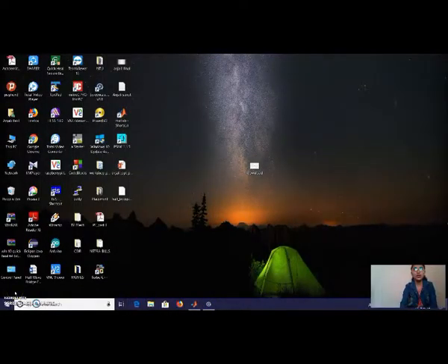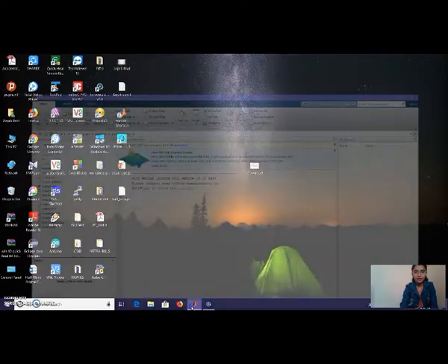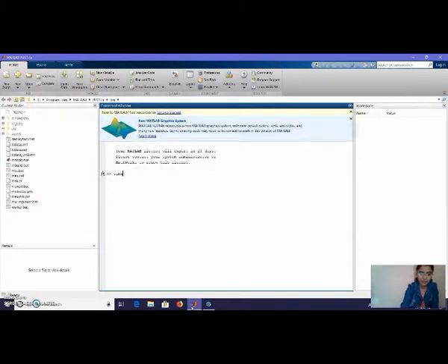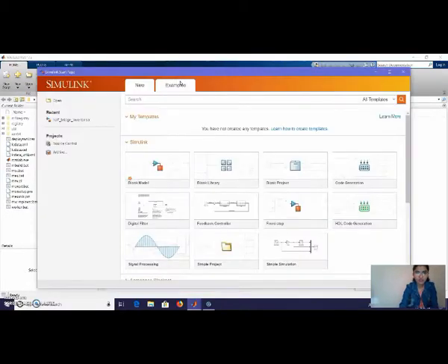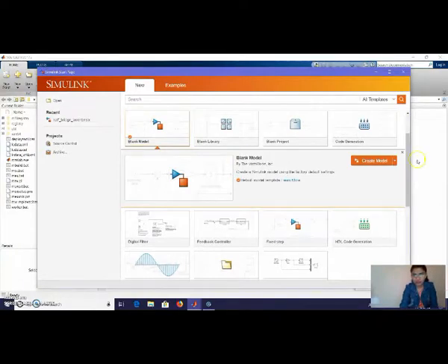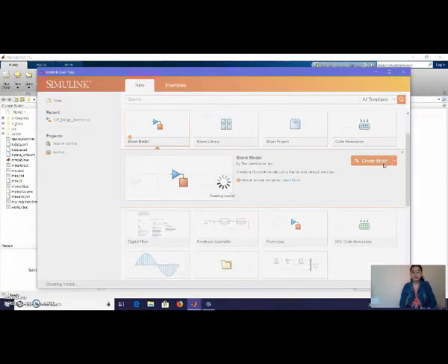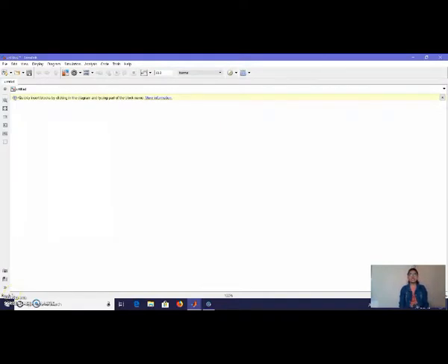For this we require Simscape and Power GUI. Open your MATLAB software. Simply type here Simulink or click on the Simulink icon. Once the Simulink start page pops up, click on blank model. So create a model. It will take some time for creating that model. Press Ctrl Shift L to open the library window. We need some components, so let us bring all those in the window.